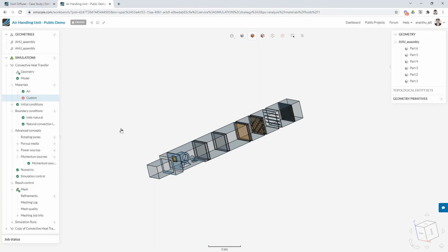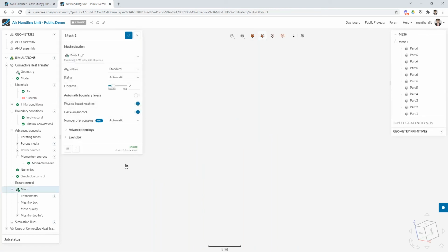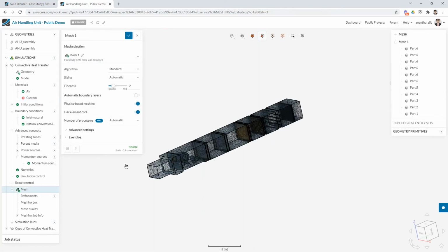And coming on to the second part, about the meshing. As I already mentioned, we did a lot of investment in actually getting the requirements from our users and the kind of meshes they are happy with, and also that convince the simulation or convergence itself. So you can simply use the default mesh settings. And if you're really specific, if you want to refine a particular region that's going to be affected by the flow, then you do have the options to create additional refinements, just like any other meshing tool.